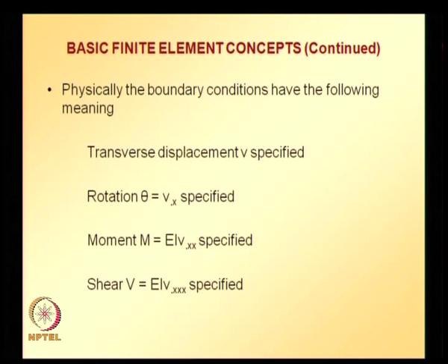Looking at the physical meaning of the terms, the boundary conditions involving V and derivative of V are essential, and the boundary conditions involving second derivative of V and third derivative of V are natural boundary conditions, and this can be verified using the thumb rule that I gave in the earlier classes.